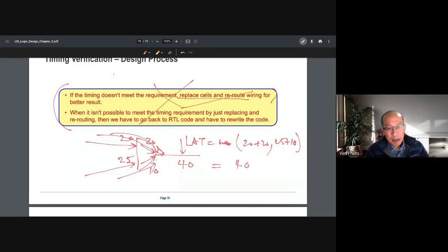No, I think even in PCB the way to prevent noise is the same, and in VLSI they have the same thing. That's why it's called shielding. The shielding is like you have the signal go forward, and along the way they have two straight wires going in parallel, and those wires are connected to the ground to prevent the noise, because everything is on the surface. And on top of it they will have a plane. On top of each chip they have the ground.